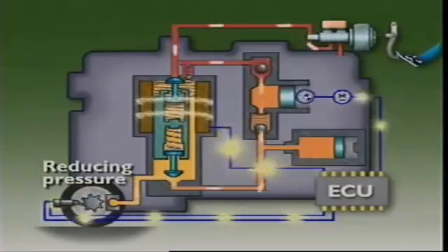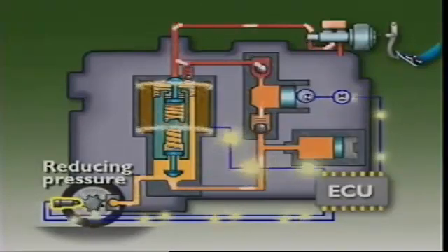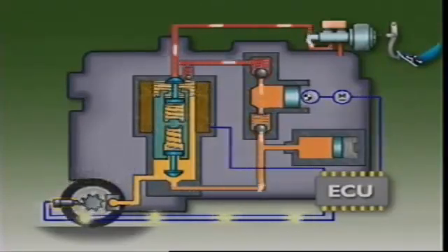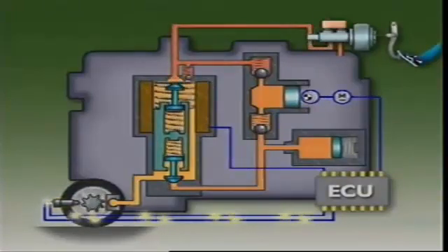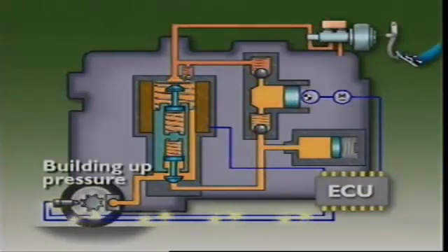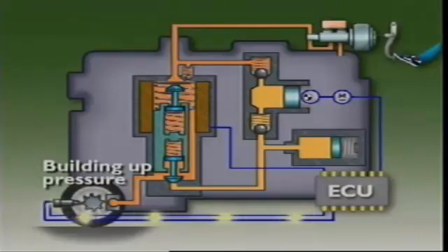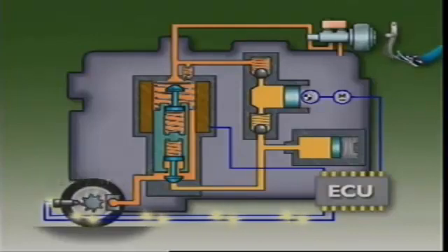If the sensors then signal the lower pressure has let the wheel speed up, the ECU stops all command current, which de-energizes the solenoid valve. The pressure rises and the wheel is again slowed down. No matter the phase of operation, pressure in the circuit can never rise above master cylinder pressure.